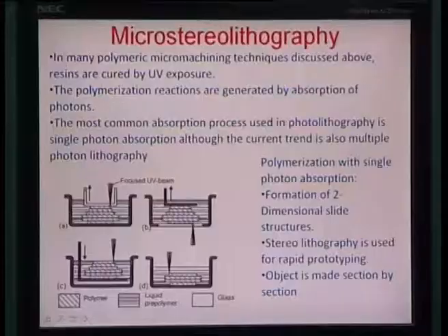Only the medium in which you are actually writing is based on photoresist. You are exposing the photoresist and trying to simultaneously cross bond the material as you keep writing layer by layer. So, here for instance is an example where this microstereolithography is done. As you see here, there are two ways of doing it. Microstereolithography can be categorized into single photon or 2 photon type of lithography, where you have slightly different nature of these processes based on their exposure methodology.